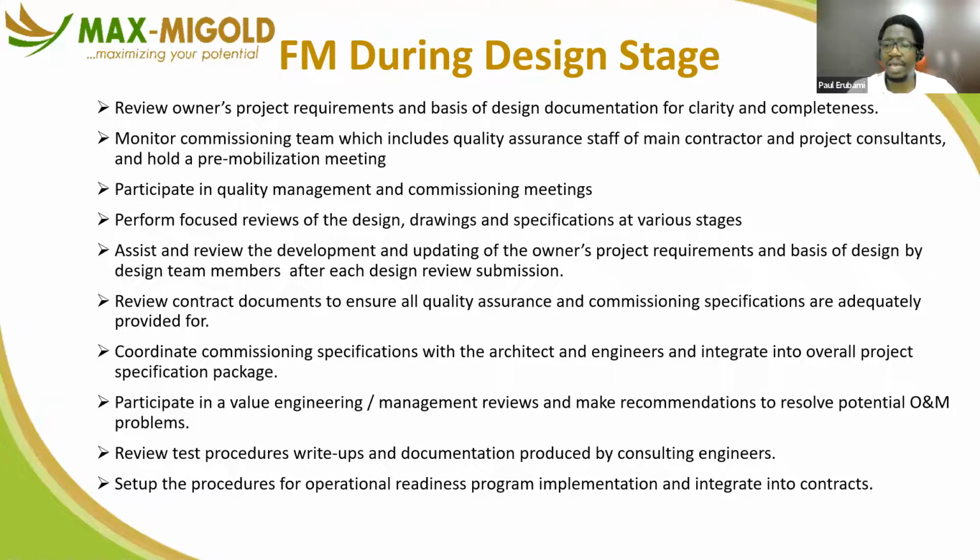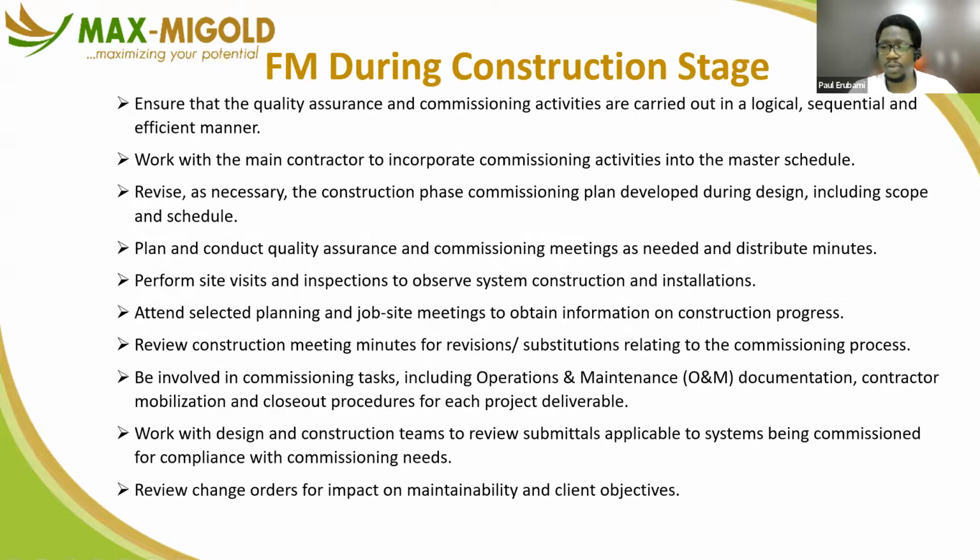No, you have to provide a line item to capture the costs of developing the as-built drawing, because as-built drawing is not just to remove the label and adjust the drawing. It's a measured drawing. You have to go back on that site after building and do measurements to get as-built drawings. So it takes effort, right? All those test procedures captured at the beginning stage, so you don't wait at that end to start saying, what are we testing, what are we trying to commission?